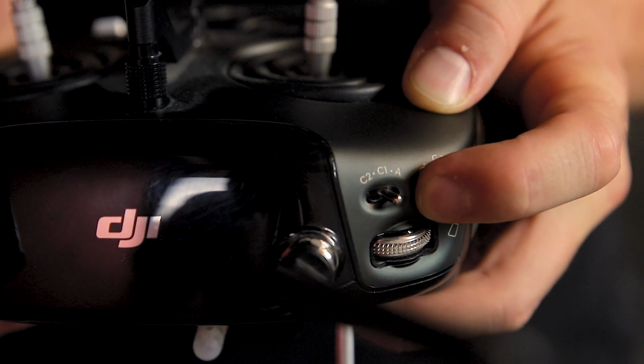The last feature of the new firmware I want to talk about is the possibility to change the default control mode. This is meant for environments with very uniform or reflective surfaces, or where there's a lot of dust. The stability system, also known as assist mode, does not perform at its best in such environments, and it is preferable to disengage it. Until now, you had to hold the bottom right function button pressed to disengage the stabilization. You can now permanently disengage the assist mode by moving the mode switch from the C1 position to A position.